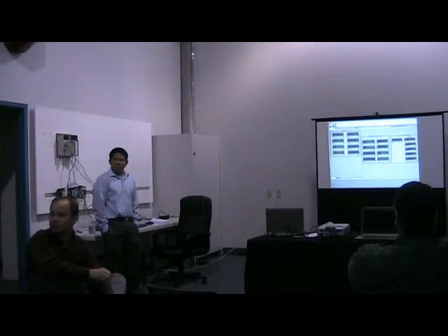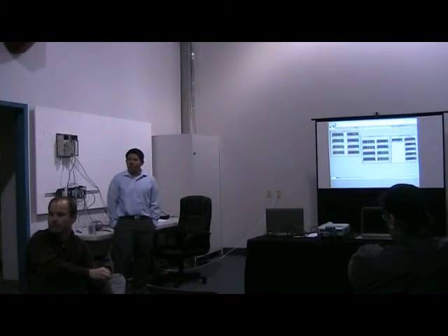That's the concern point. That happened 10, 12 years ago. What he wanted to read, and they were just doing 3 and 4 point calibration, and we found out that zero shifting was killing us. Our overall system error was up to 4.5%, 5%. And that doesn't sound like a lot. Let's put that in perspective.